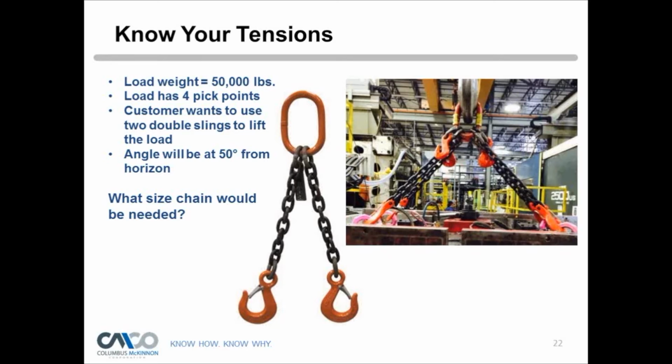So you cannot use all 4. There is no loophole by doing that. If I use 2 double slings, that's 2 double sling ratings, and then I can get more rating? No, you can't do that. You still have to size it as a quad, and we'll go through the exercise of doing that.